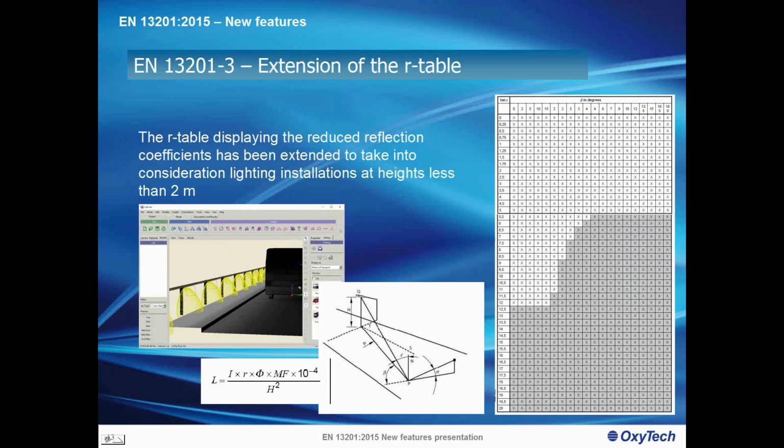So as we were saying, the new standard is introducing the calculation of the TI, also considering luminaires placed at a height lower than 2 meters. But in order to run the calculation in this way, and also to consider this situation, it is necessary to expand the matrix of the R tables. So the white ones are the values corresponding to the old R tables, so the famous C1, C2, or the old R1 up to R4, for example.